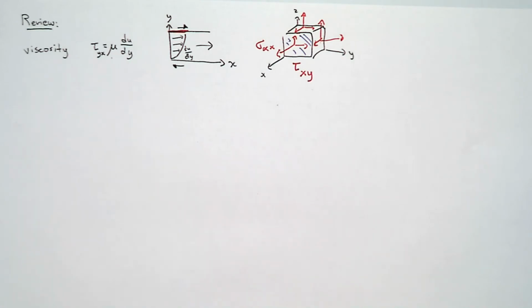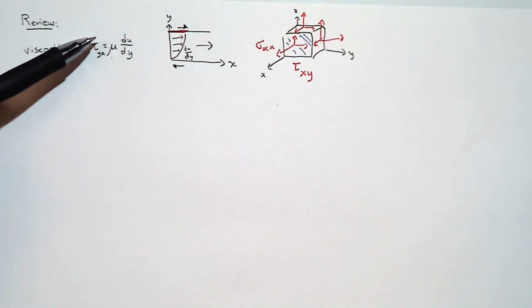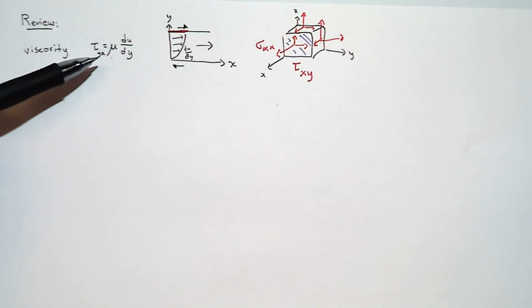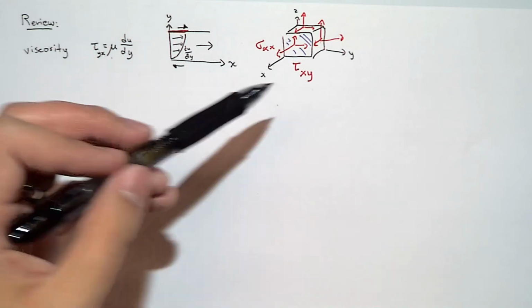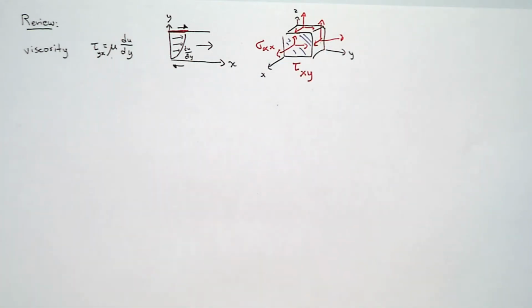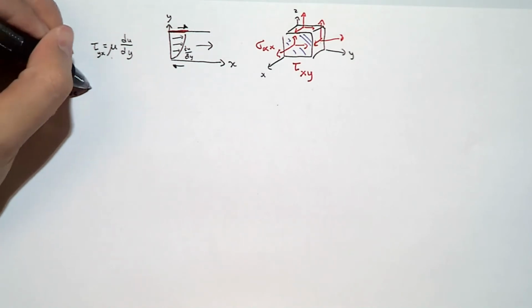And if we repeat these experiments for multiple types of fluids in multiple directions for three-dimensional flows, we are going to land at a series of equations that give you the relationship between shear stress acting on each face of a fluid to its viscosity and its velocity gradient. Now, these equations combined are known as the constitutive equations.